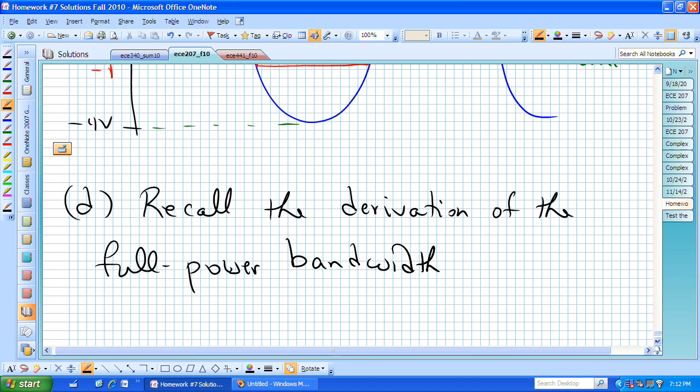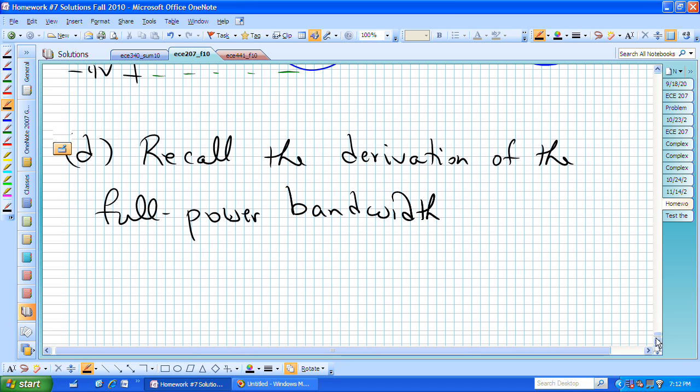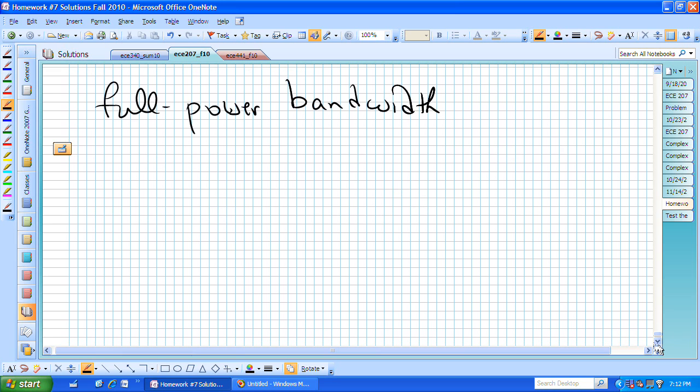What we were doing there is saying that because of the slew rate limit, or the speed of our op-amp circuit, we can only achieve so much slope change, or we have a maximum time rate of change of our output voltage with respect to time.